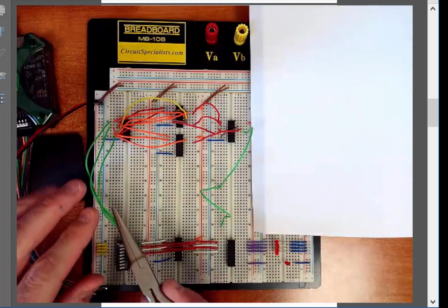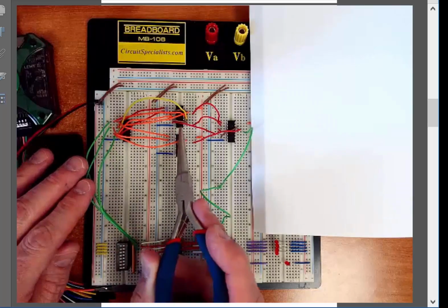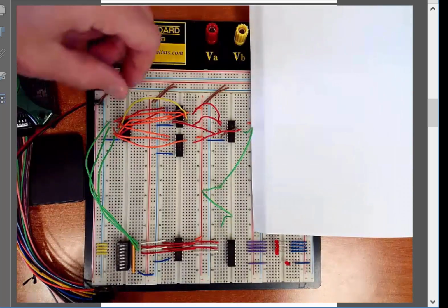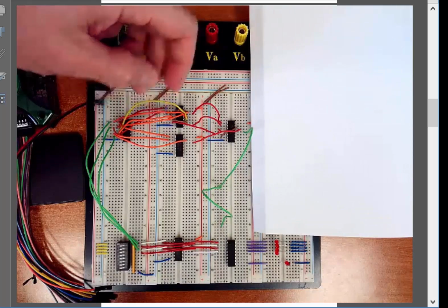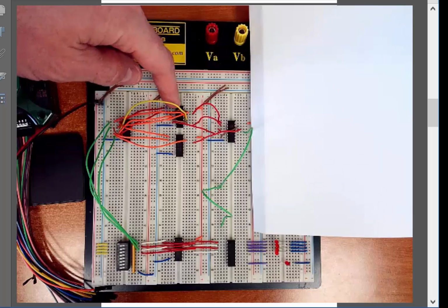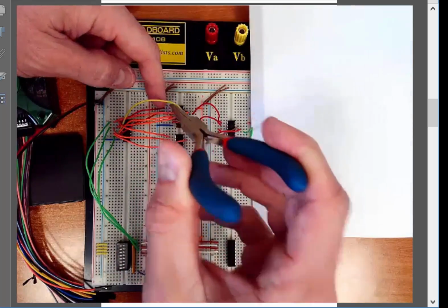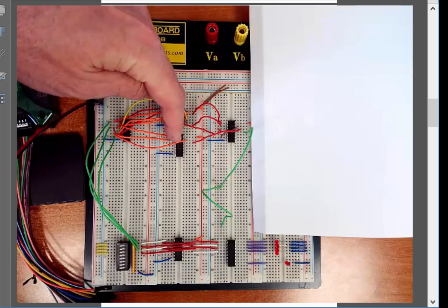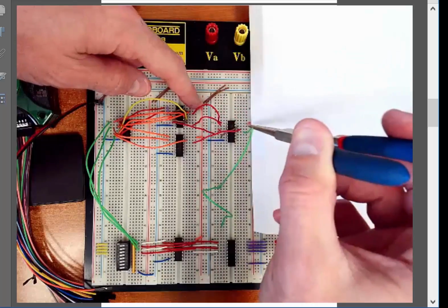So what I did is I brought my 3 inputs up here, A, B, and C, and I created inversions of all of them, and then I used them to create my 4 min-term logic expressions within these gates. You can do it however you want. I built the first min-term up here, and the first min-term was A naught, B, C naught. When I went to build it, I said, well, I've got A naught right here, so I just jumpered it down using that purple wire. However you want to do it, you build up those 3-input AND terms, and then you bring the 4 terms over here, OR those together using 2-input OR gates, and this is my output right here.